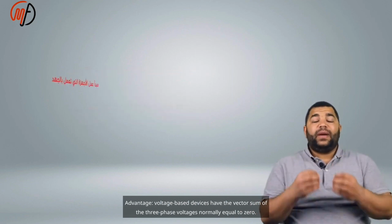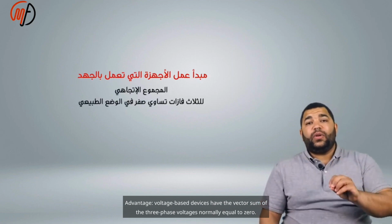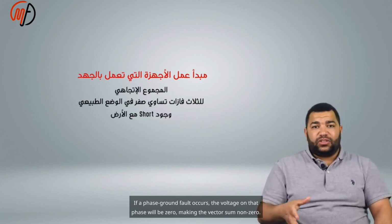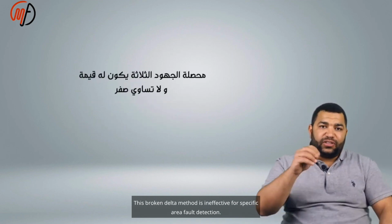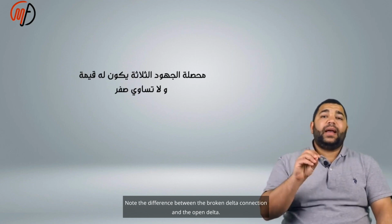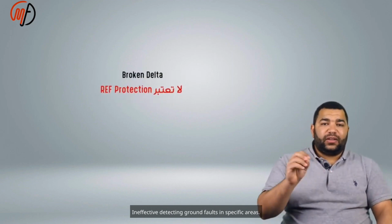The advantage of voltage-based devices is that the vector sum of the three-phase voltages is normally equal to 0. If a phase-to-ground fault occurs, the voltage on that phase will be 0, making the vector sum non-zero. This broken delta method is ineffective for detecting ground faults in specific areas. Note the difference between the broken delta connection and the open delta.